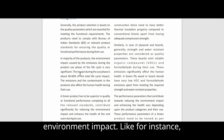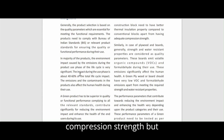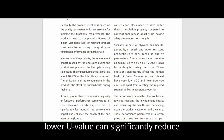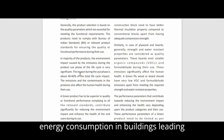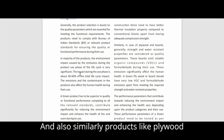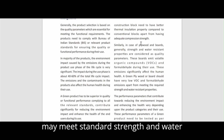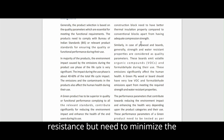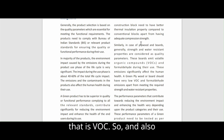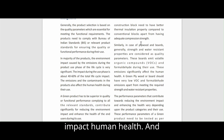For instance, construction blocks may have a strong compression strength, but incorporating thermal insulation like lower U value can significantly reduce energy consumption in buildings, leading to a lower overall environmental impact. Similarly, products like plywood may meet standard strength and water resistance, but need to minimize the emissions of volatile organic compounds, that is VOC, and also formaldehyde, which can negatively impact human health.